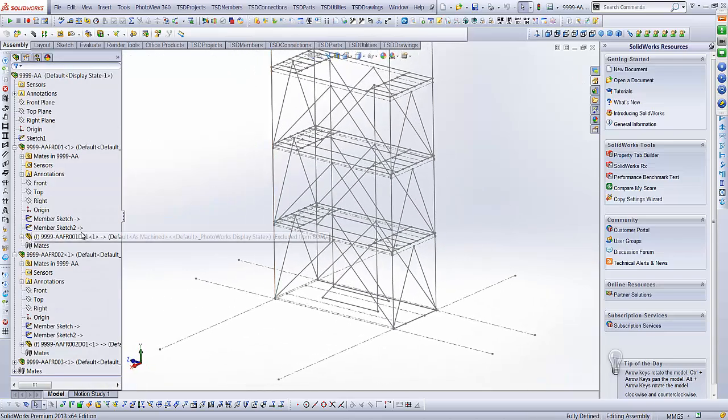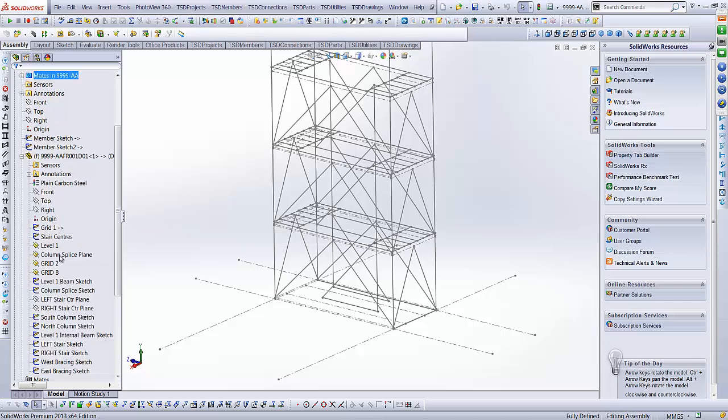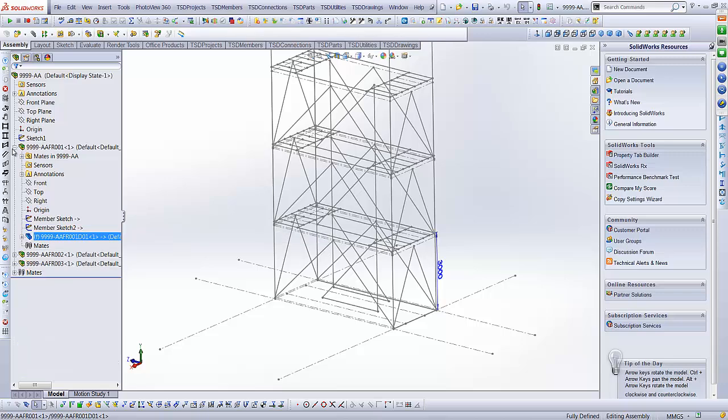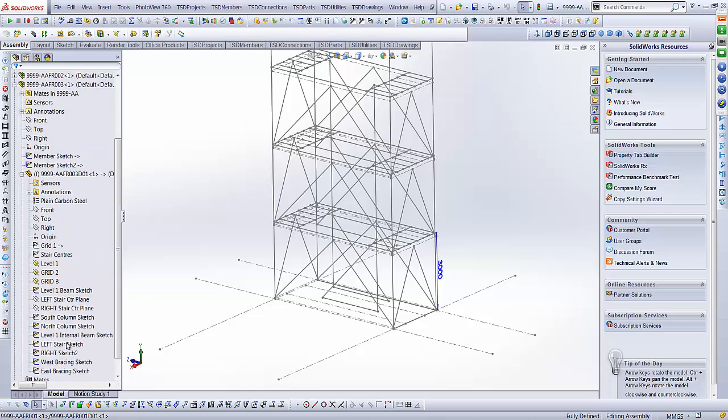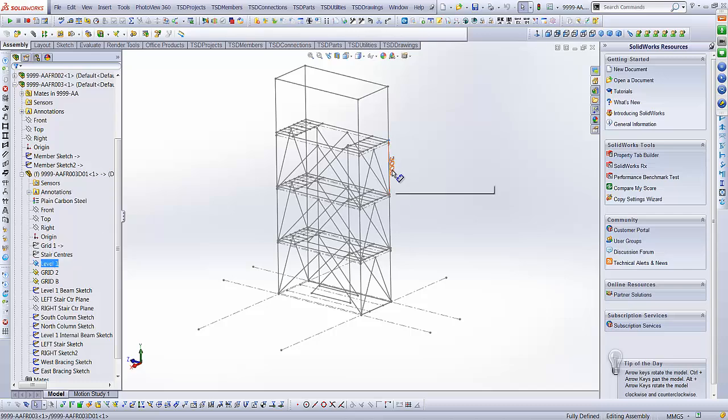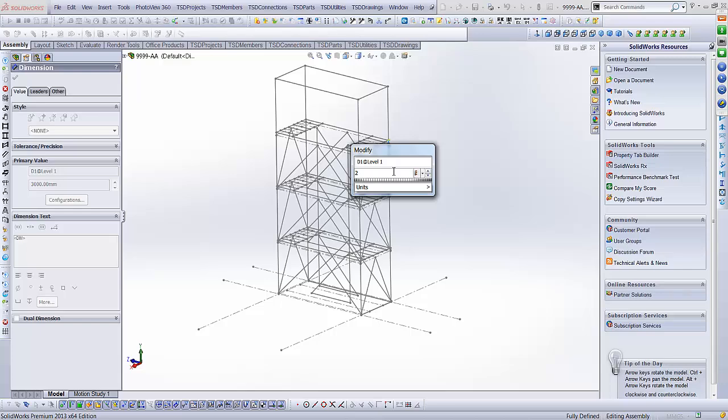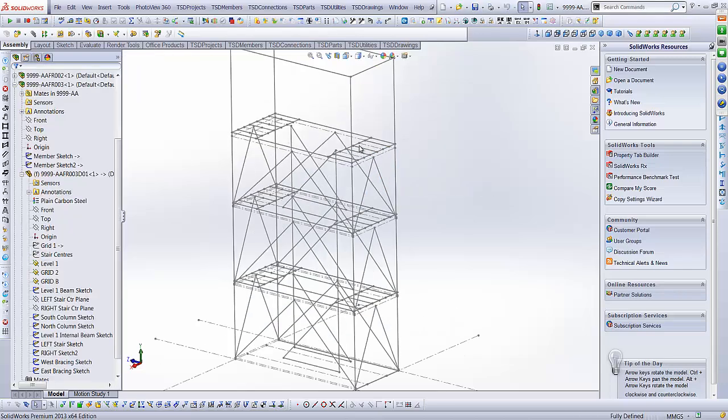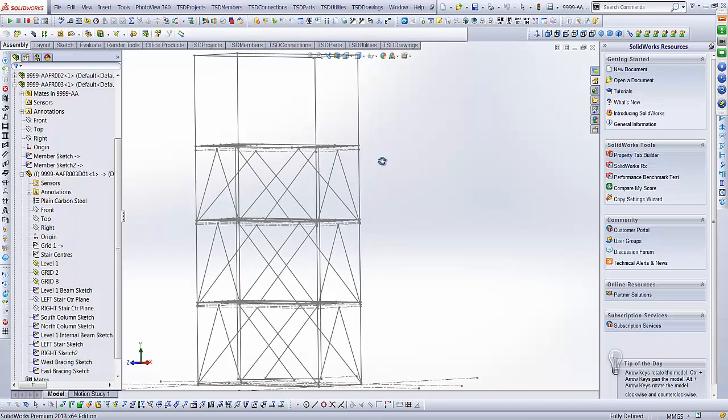Okay, they're all configurable and changeable, so I can go in and just simply select, let's say, the floor height. So level 1 in that one can be changed to a different height. Now I'm just going to grab the top one. I'm just going to show you how this works so that you can see how stairs automatically update. I've labelled these, haven't I? Level 1, there we go. Oh, didn't double click it, do it again. There we go, level 1, and I'll just change that to say 2700. And you'll notice the change, so the whole floor changed then. So we've got a different height on that one.